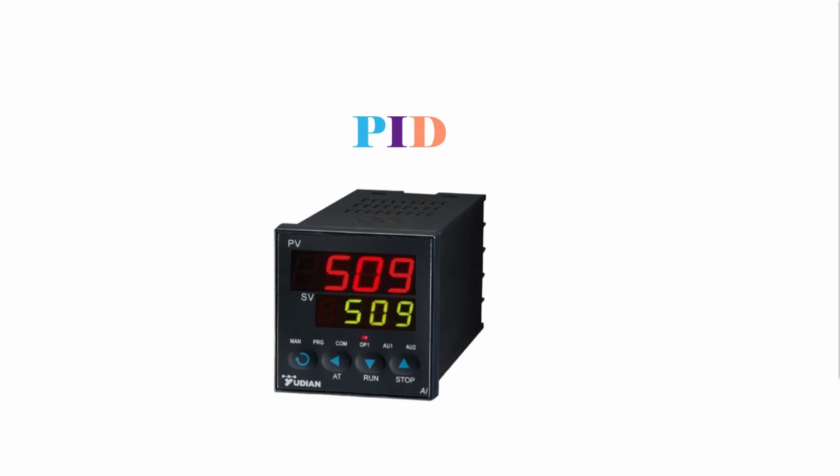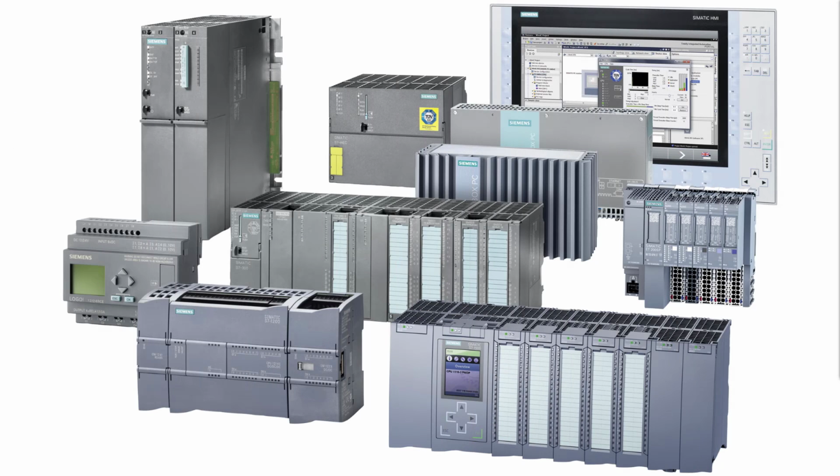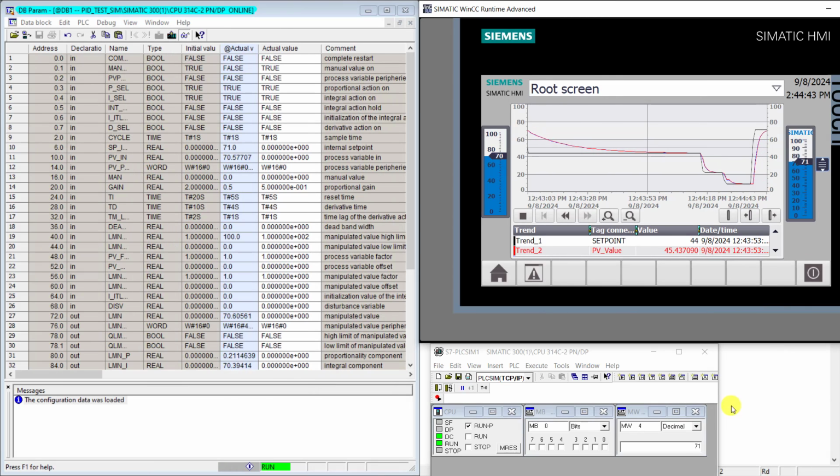PID is an acronym that stands for Proportional, Integral, and Derivative control. It can basically exist as a physical standalone unit or a function block in a PLC controller, such as Siemens, Allen Bradley, etc. The PID section of modern controllers is a series of numbers that are used as adjustments in order to achieve process objectives.